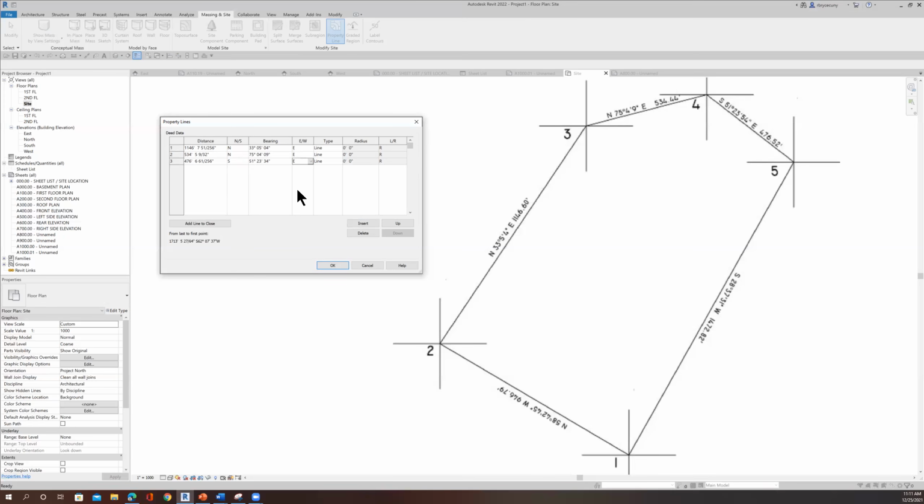We'll go over here now. So I insert, and let's see, the distance is 1472.82. And then southwest. Okay, so we'll change this to south, and we'll change this to west, and then we'll put in the bearing, which is 28, 37, 31. 28 space 37 space 31.